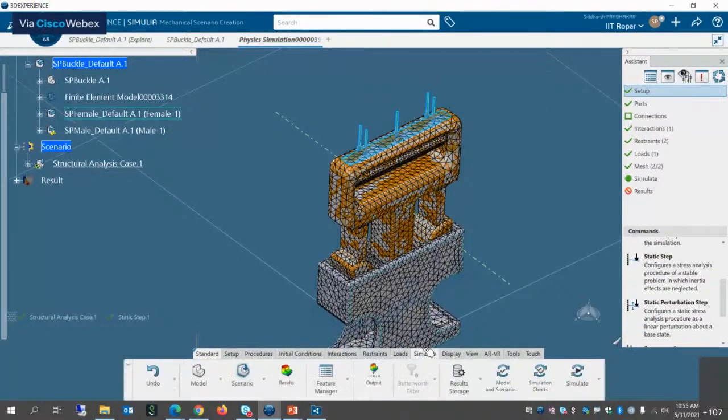And now that we have all of it created, you can see there is a simulate option here, right? So simulate, basically what you can do is there are three options again below here. So you have model and scenario checks. Basically it does not simulate your model, it will just check for any errors or anything that you have missed. So if it's a very complex simulation that you're trying to do, you obviously do not want the simulation to fail in the end just because of a failed step. So model and checks is a short way of doing it, or the assistance option as well.